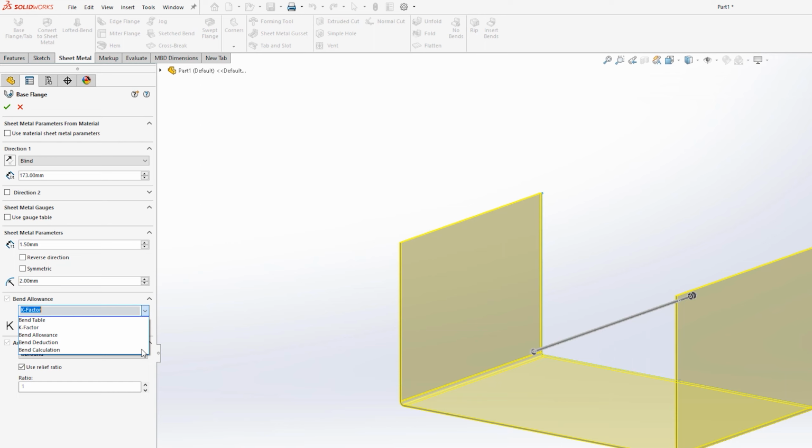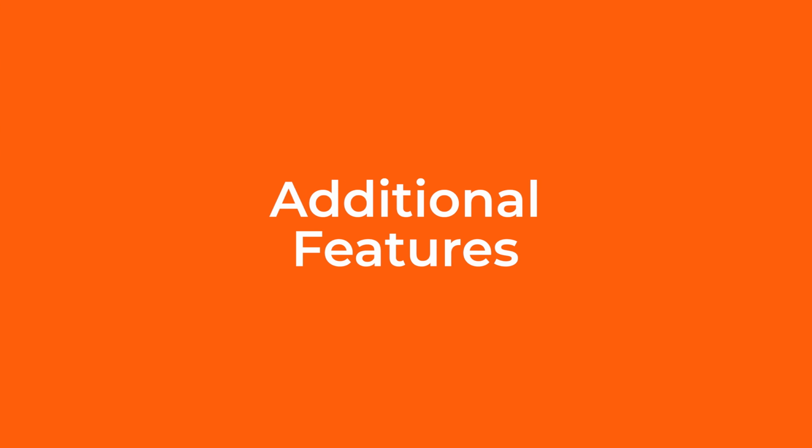Sheet metal manufacturers should know these values, but for engineers designing sheet metal parts, be careful when supplying flattened parts for profiling and laser cutting, as an incorrect value here will result in an incorrect part. Relief controls how the corners where two flanges meet are treated. This can be set to tear, obround or rectangular.